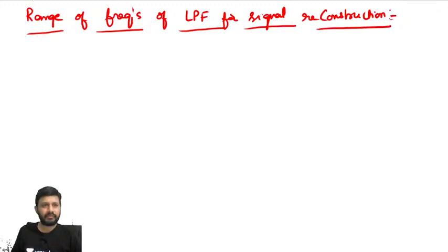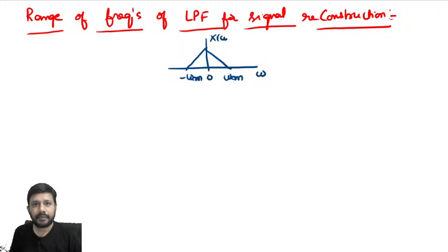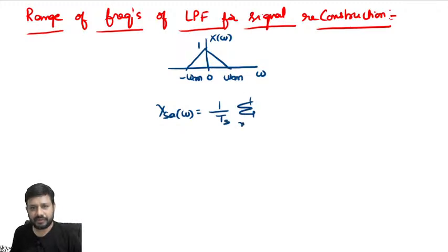Again, we can show it like this. We started with a band limited signal. Okay, we took a band limited signal. Now we sampled. What happens if you sample? If you sample a signal in the time domain, periodical repetition is going to occur in the frequency domain, given by this expression. Sample spectrum. This you have to remember, very very important.